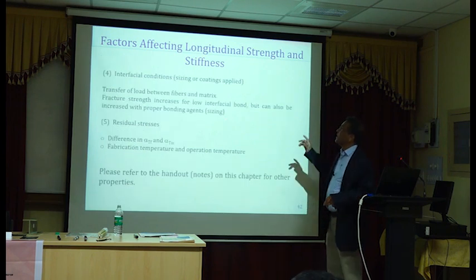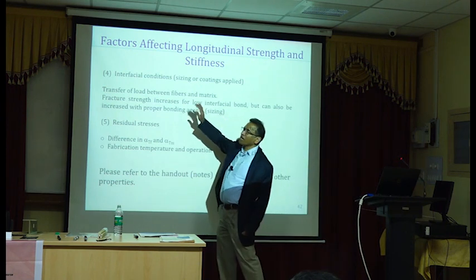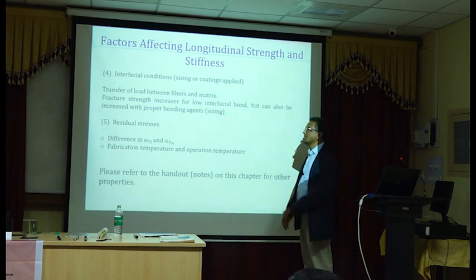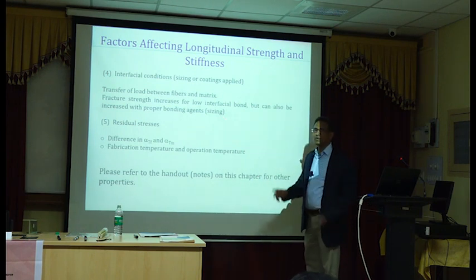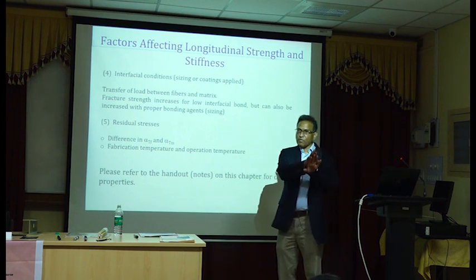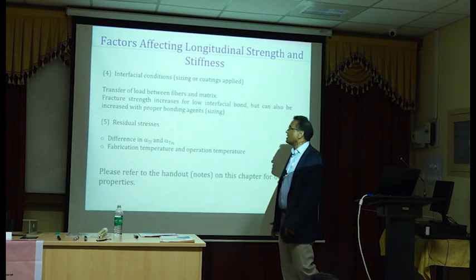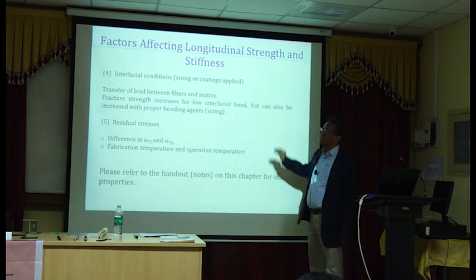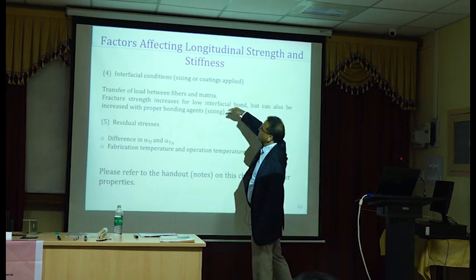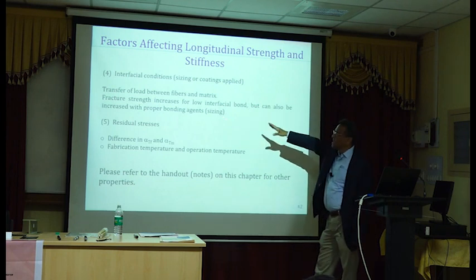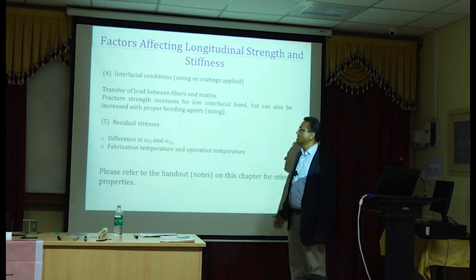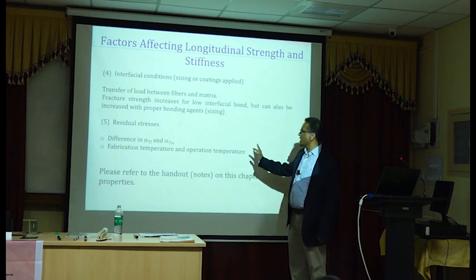And then you definitely remember, if you forget everything else from this micromechanics and processes, that's okay. But remember sizing. Don't mix the sizing. Concrete needs one type of sizing. Composites need a different type of sizing. Sizing is the coating on the surface of the fiber. Okay, so make sure you use the proper sizing. There can be residual stresses because of difference in coefficient of thermal expansion and things like that.